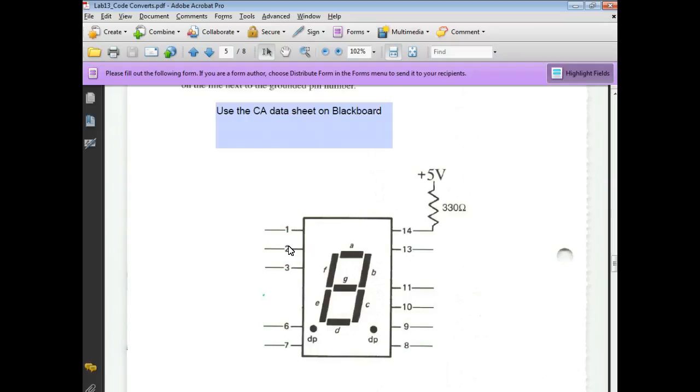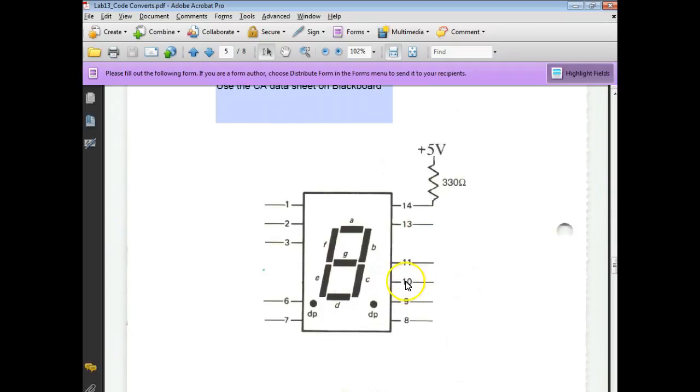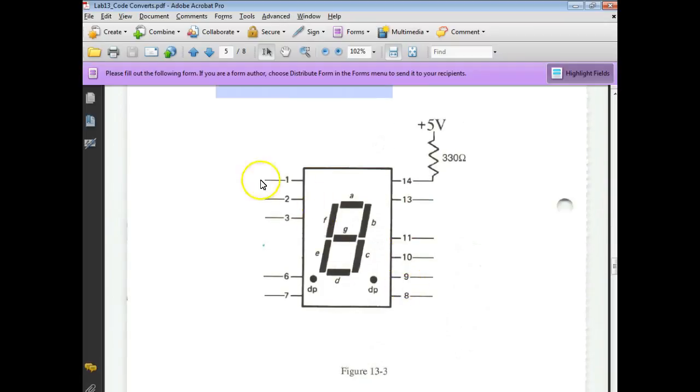That makes sense? Then you'd take a resistor, hook it up to one of your power pins, then take the other polarity and try to turn an LED on. If none of them turned on, then instead of using 5 volts, I would connect it to common, and then try to figure out how that thing works. I wish I still had that other one up here to show you how to do that. So normally on a 7-segment display, you can figure that out.